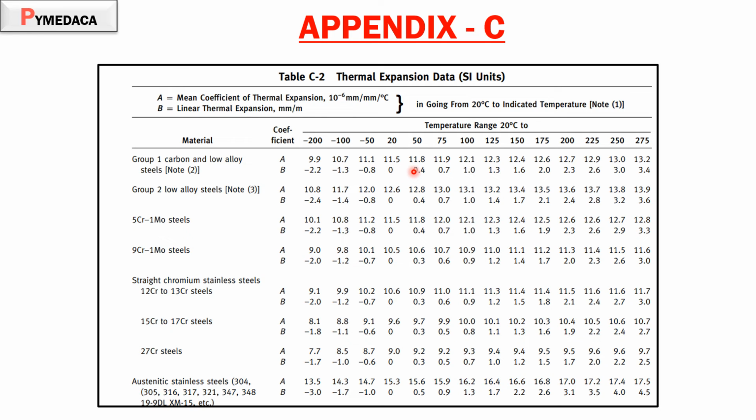But you have to understand as a mechanical engineer that all materials expand, even at 1 degree or 2 degrees. If there is a difference in temperature, it expands. But if the expansion is negligible, then we will consider it as 0. So here we can consider that somewhere around 8 mm it will expand for 10 meters, right?